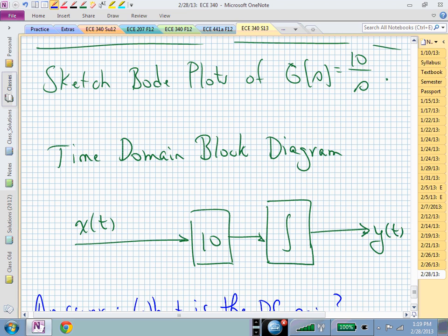You're giving me the gain of the constant, aren't you? So I want to make sure that we're clear on this. We do identify constants, and we find the gain of that constant, but that's not necessarily the same as the DC gain. It's not going to be the same if you have poles or zeros at the origin, and I want to make sure that's clear.